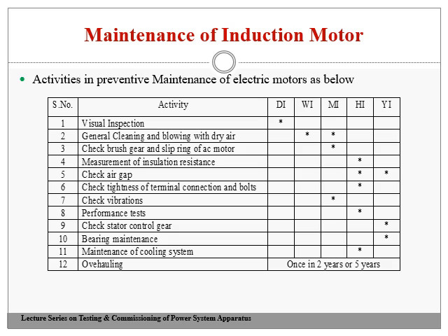Check for vibrations. It can be a monthly activity as per the standard, but it can be done even half yearly if it is required, depending upon how many hours that particular induction motor is operated. The performance test can be done half yearly, or if it is scheduled or unscheduled, you can do it anytime as such.